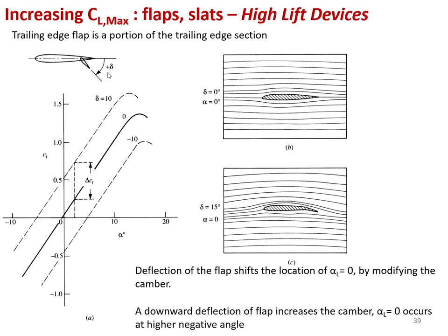Okay, let's look at an example of the trailing edge flap. Trailing edge flap is installed at the back of the airfoil, and essentially it means that you can rotate the trailing edge. If you rotate the trailing edge in the positive direction, which is defined as this direction, then you are effectively increasing the camber of the airfoil.